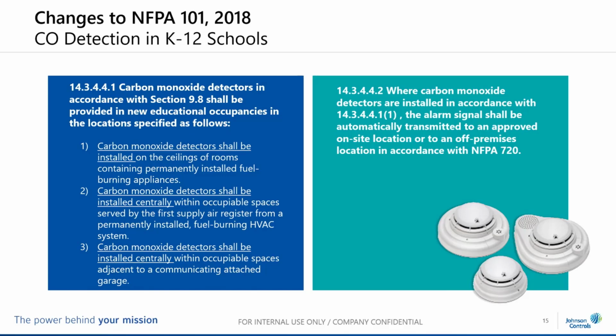And Section 14.3.4.4.2 is new, and it requires CO detectors to automatically send the alarm signal to an approved on-site or off-site location in accordance with 7.2.0. So now we're looking for these devices to be supervised, sending a signal to somebody that may be at a desk 24 hours a day, like an operator station or security station, or sending it off-premises, kind of like we do with fire alarm, to a supervising station.